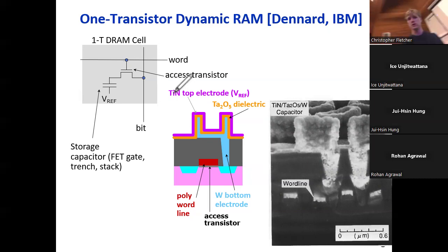Okay, so what I'm going to do is similar to last time we did this. I'm going to spin this around so that I can see what I'm doing. So the way to view this cell, forget about how multiple cells are dealt with. Let's just live in a world where we want to store a single bit in this entire DRAM. The way to look at this cell is the horizontal wire is like the address. It's a 1-bit memory, so we just have one address bit. And the vertical wire labeled bit or bit line is like your output bus, your data out.